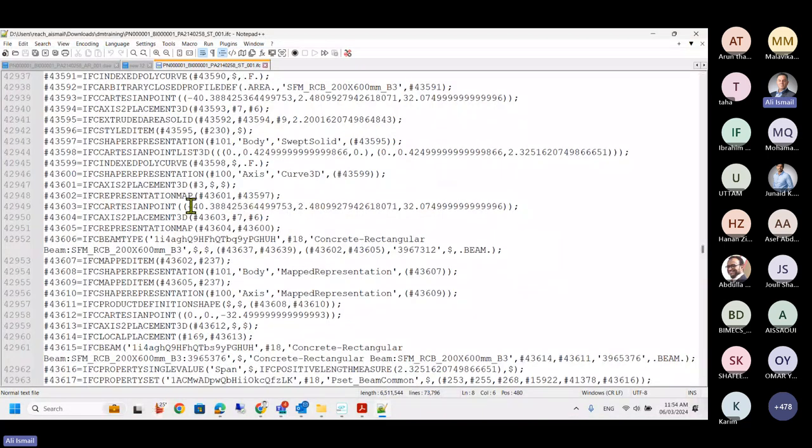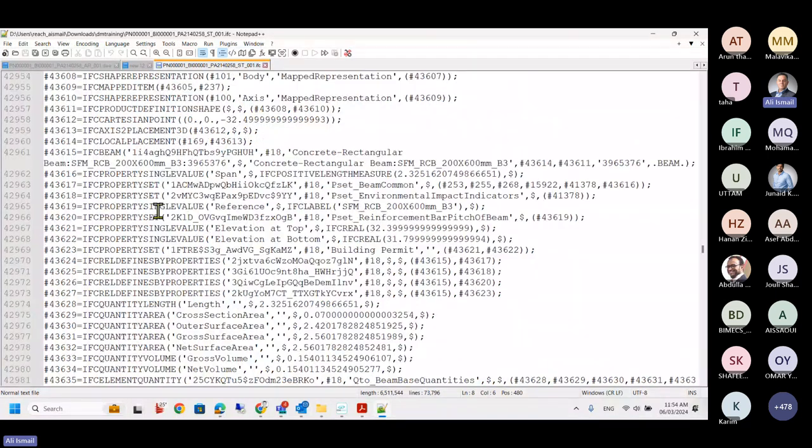But of course, you should, to a certain level, understand how the geometry inside the model is defined, how the geometry is generated, how the relationships between elements are described, how the alphanumerical information is attached, how the hierarchical relationship between site, building, floor, and then spaces is described in this model.